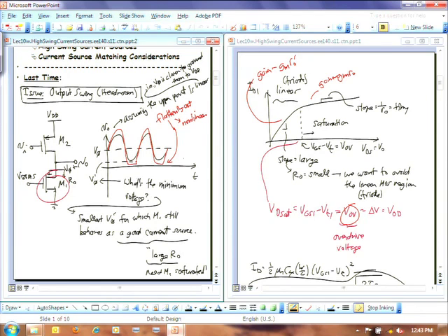We went through the analysis here and we thought about the transfer characteristic for a transistor, the ID versus VDS curves, and we recalled that these curves were nonlinear. And so usually we're operating in this region here where the transistor is saturated. But if your output makes too large an excursion, say downward in this case for this circuit, then your VDS for M1 becomes too small.